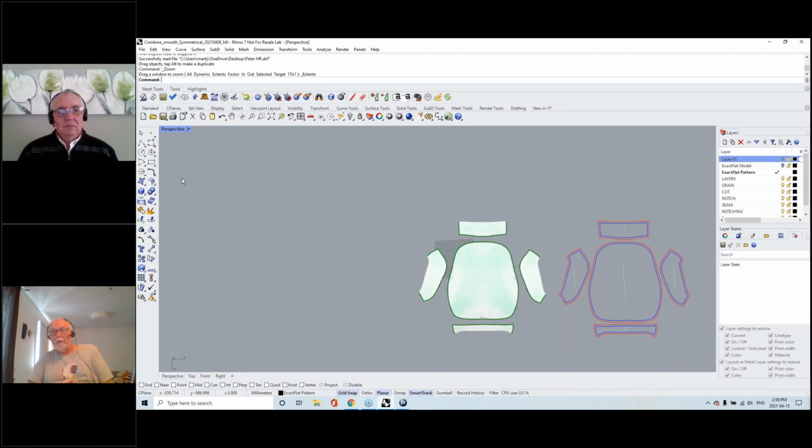Yes, it is. Again, you put targets on it. The scanner can track by three things: targets alone, targets and unique geometry, or even targets, geometry, and texture, which is the scanning world's word for color picture. So we almost all the time track by targets and geometry. But if I was to scan a soccer ball, which is perfectly round in theory, the scanner can't know what point of view it has on that. But if I pointed at a human face, it knows immediately because there's geometrical detail. So it can tell that it's moved sideways, but it can't tell if it's moving along a flat table. So we always use targets.